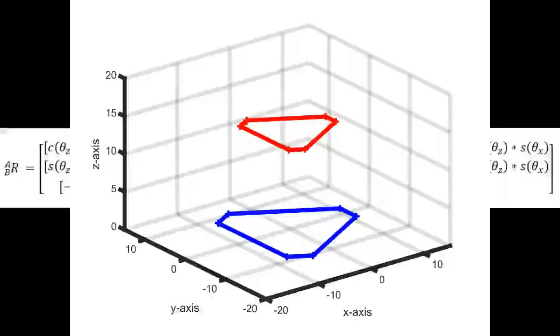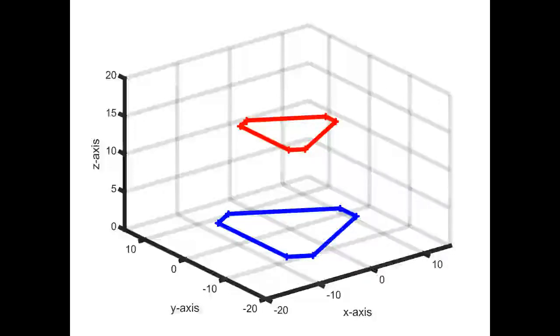A vector theta equals theta x, theta y, theta z is expressed as the orientation of the top platform with respect to the base frame. Therefore, the location of the top platform with respect to the fixed frame, in terms of location and alignment parameters, is articulated as Px, Py, Pz, theta x, theta y, theta z.